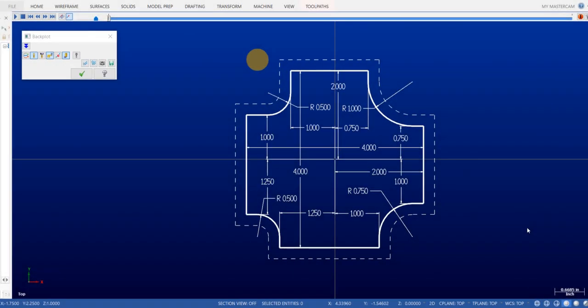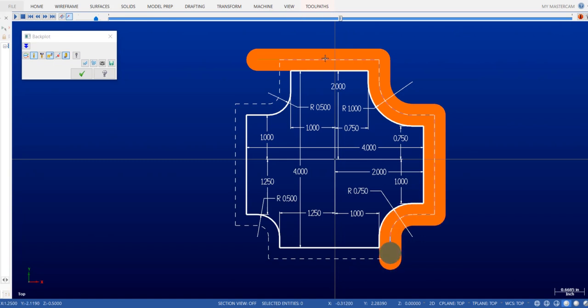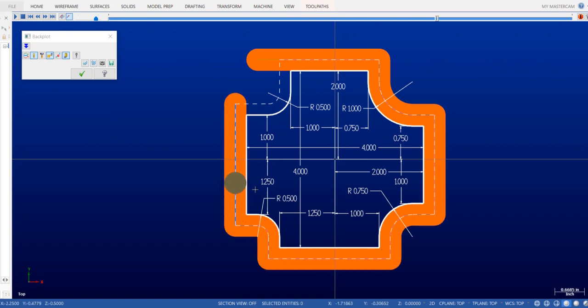Alright, in this video we're going to talk about adding cutter compensation to our toolpaths. So far we've learned how to write a toolpath, offset half the distance around our profile, and do a tangent move in line with our first piece of geometry and then a tangent exit when we come off of the part.